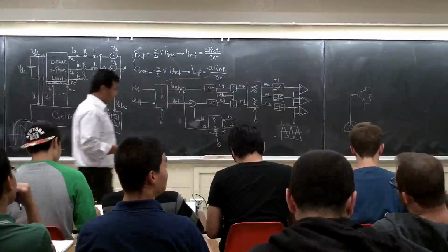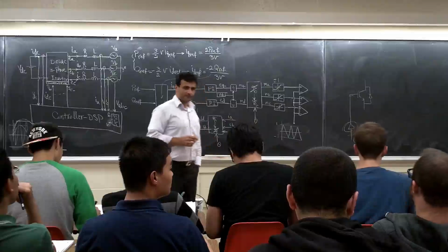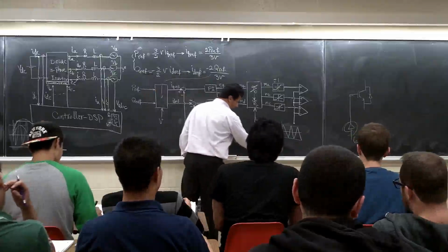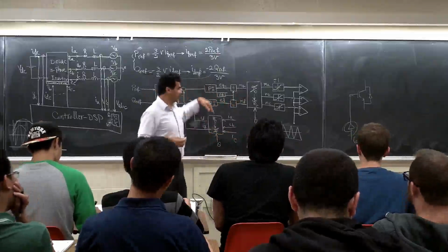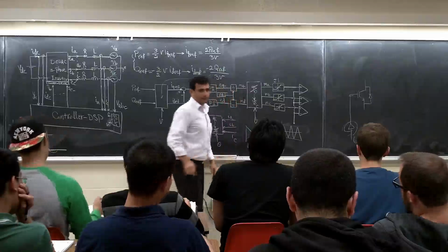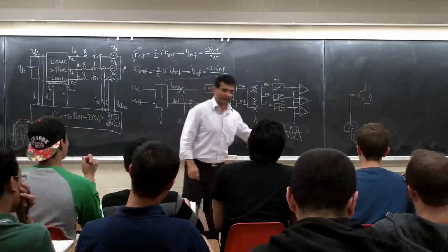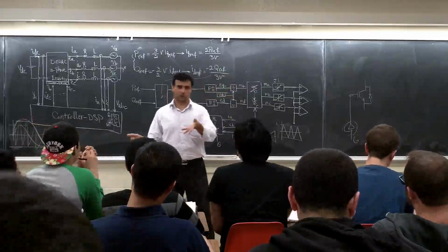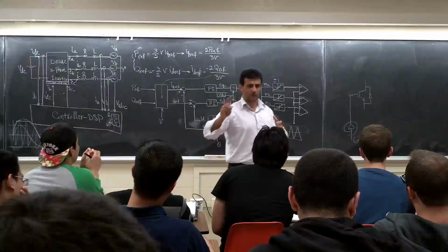Right. Why is it we always use the triangle wave? Why not? You can use the sawtooth if you want, you can use this one, or you can use down, you can go with this one. Did you use a sine wave? No, it has to be a carrier waveform, it cannot be sine. Remember, we went through why we use this carrier.